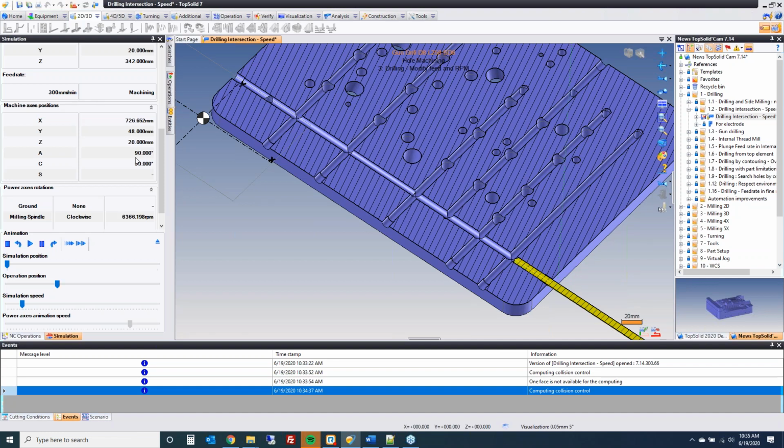But you'll see as we break through, two things happen. I did tell it to slow down the feed rate. So here we're at 300, and notice here, we're now 20% less on the RPM, or maybe you want to go 20% more, it's up to you, okay? Now we're breaking through, and now we're back up to the program.